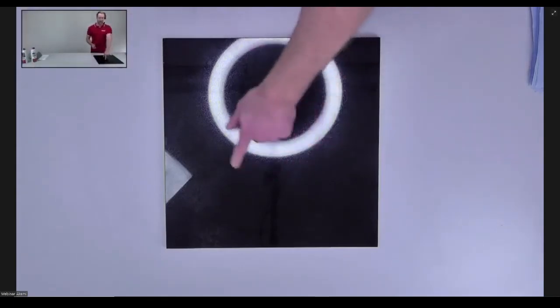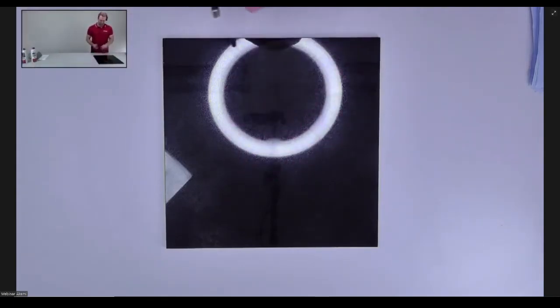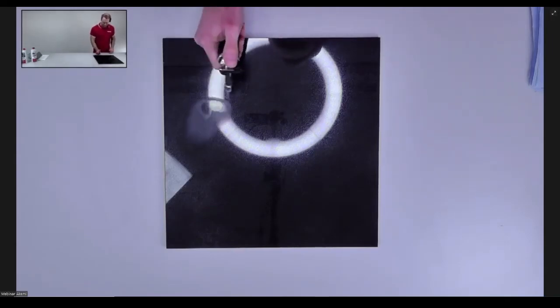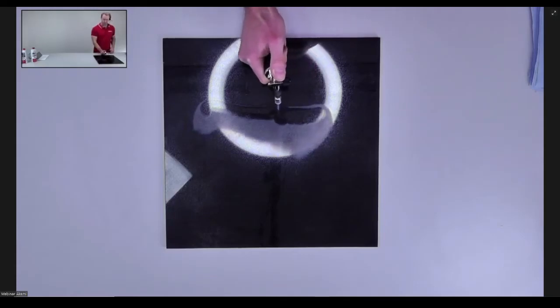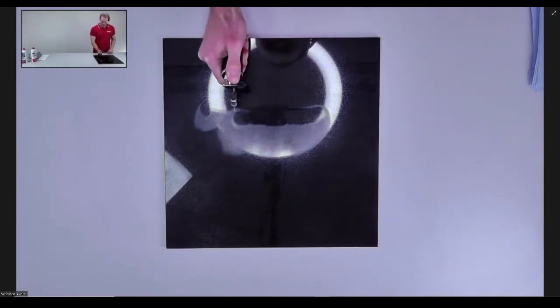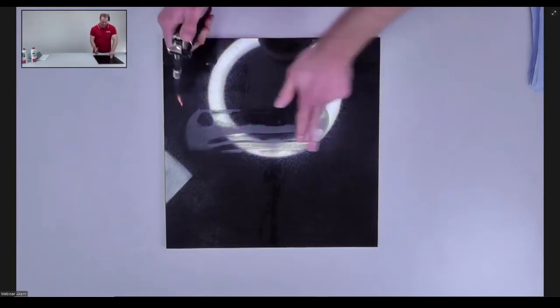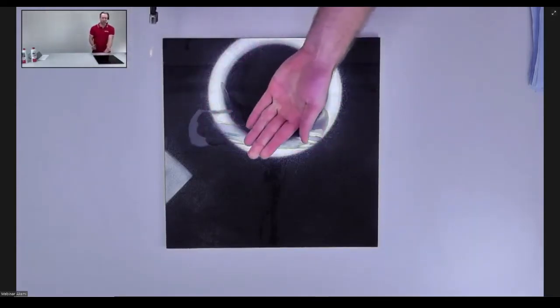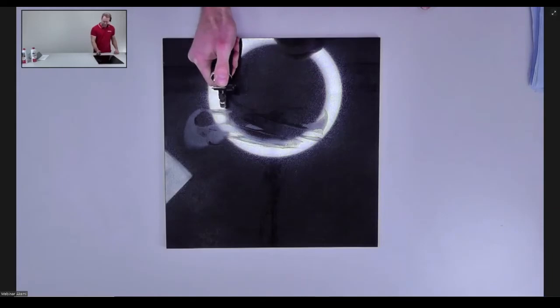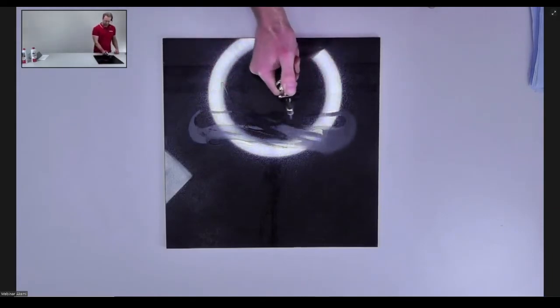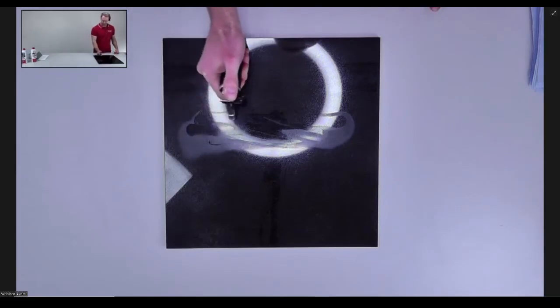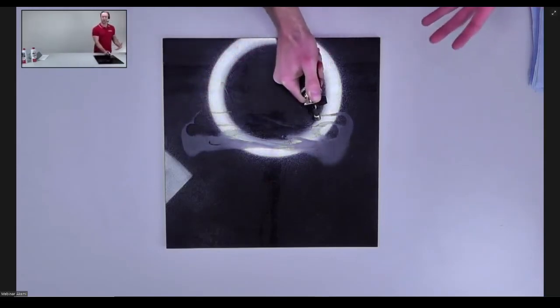So now when I go on the stone with the flame, you can see directly how the stone starts to sweat. Here's the water. This is all water. Here you really have to be sure that your stone is dry. You need to go with the flame several minutes over the stone, especially when you have kitchen countertops, where you have big pieces, where you want to be sure that the treatment is right, what you're doing.